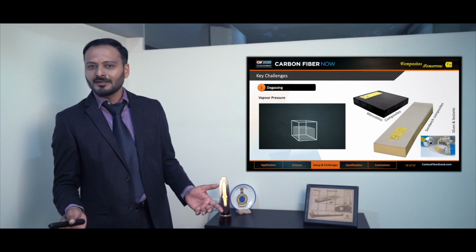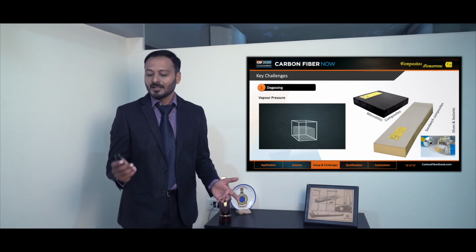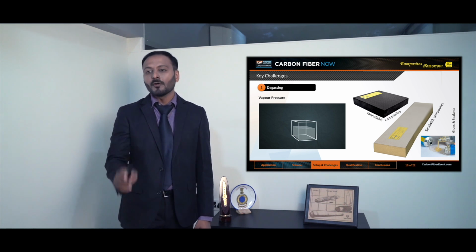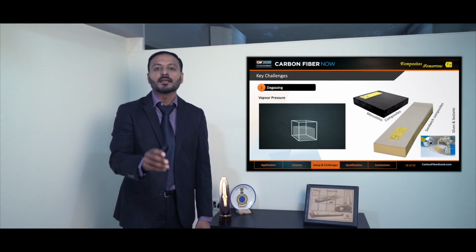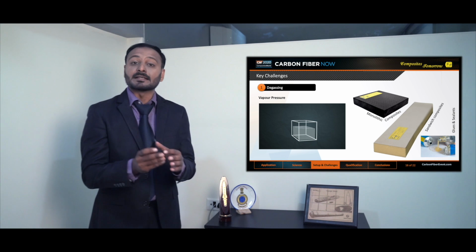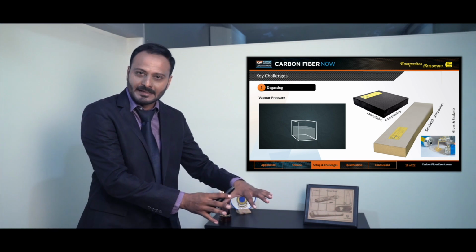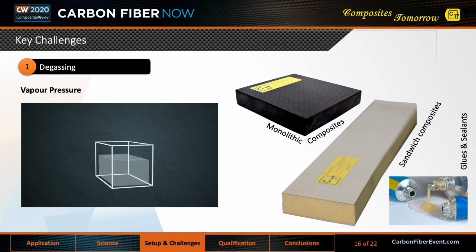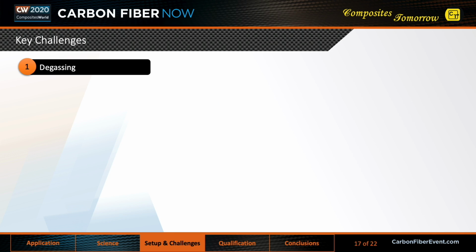But of course we are there to relieve you from troubles. And the solution to degassing? Simple. Before putting your product in the sputtering tank, it is advisable to have a separate degassing chamber. You take it to, let's say, 85 degrees centigrade at 10 raised to minus 3 millibar vacuum, and you have a shell that is already degassed at 30 minutes and ready for sputtering.